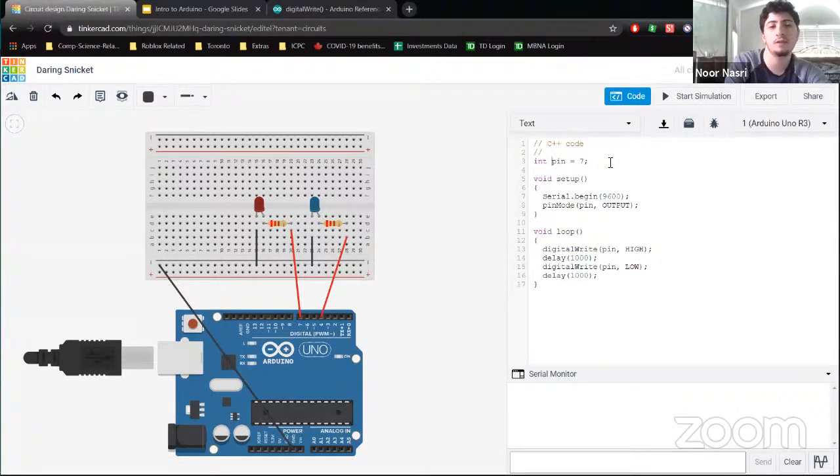I'm just going to change the names a little. So let's say red pin, and then we're going to have blue, which is just going to be wherever we connected it to, 4. You can use the ones that have the squiggly next to it. It'll digital write just fine. It'll also have other functions, so sometimes we try not to use it for these things.